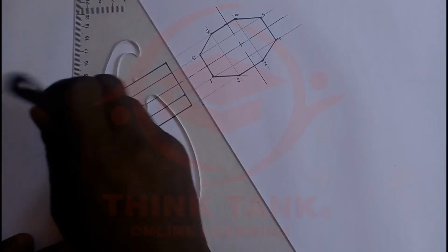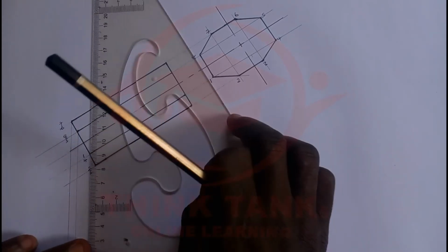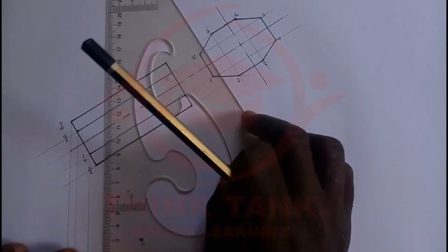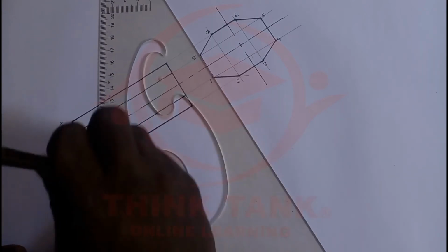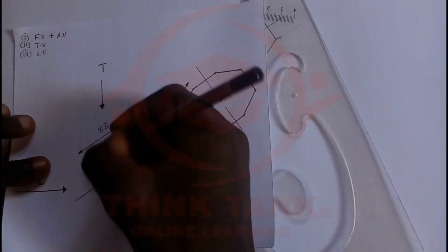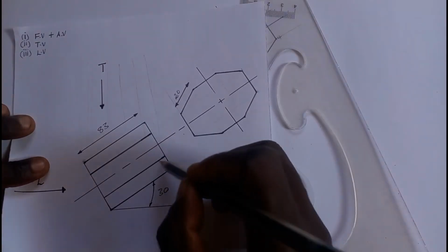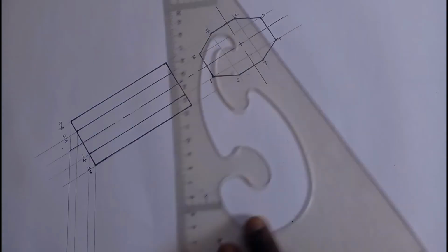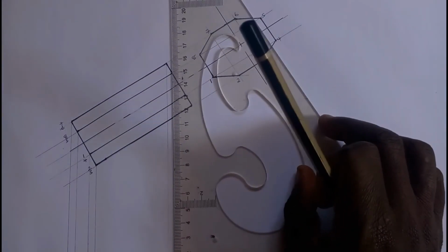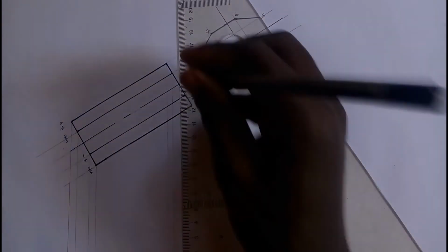I'm going to project them downwards. The one that we're drawing now is the top view. On the top view, as you can see, if we project some lines right here, you're just going to see this point, but if you project them right around here, you're going to see this face. I'm going to do the same right here and project lines right here.